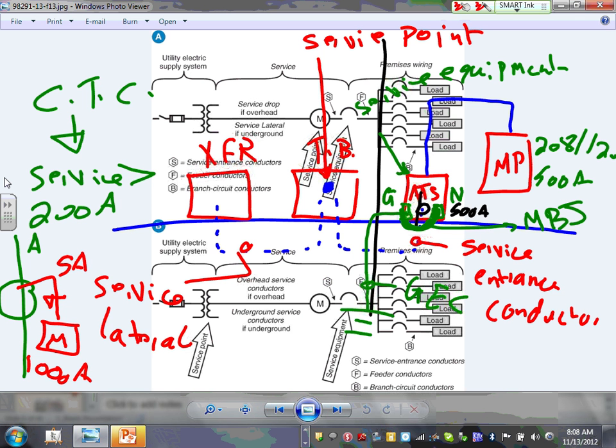And then, of course, the meter is going to have voltage coming to it too. So with the voltage and the amps reduced, you can run the meter with 120 or 277 volts. You can measure the kilowatt hours that you need to charge the customers for. Any comments, any questions about this? Can I get you to understand this one? Because the rest of it is history if you understand this picture.